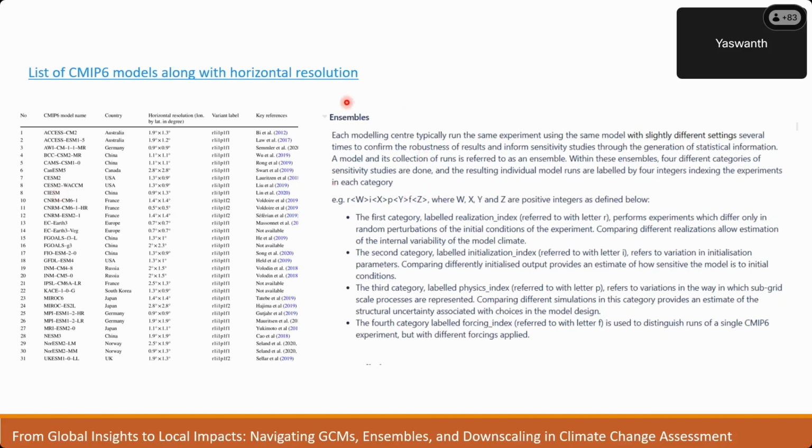So when it comes to ensembles, the terminology we use is running the same model with different initial conditions or different physics options. As I've shown with 12 different combinations of WRF output rainfall, the scientists also run their models with slightly different initial conditions and slightly different physics combinations. Sometimes they run the model with 3 to 4 different boundary layer combinations because these are complex simulations which are highly dependent on the cumulus options and microphysics options. So they try with different ones. For example, you run the hydrological model with the SCS Curve Number method or Green-Ampt or different ones, and see what the discharge is.